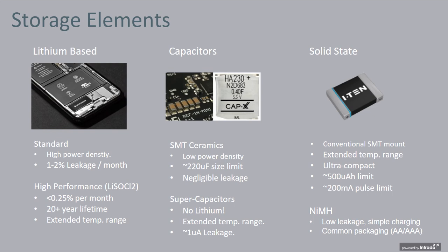If you want longer runtime, you could opt for a supercapacitor. If you want hours of runtime or days or maybe even a week, you can use a super cap. They're going to be a little bit larger size, more similar to a lithium polymer type battery. But again, you get that longer runtime.